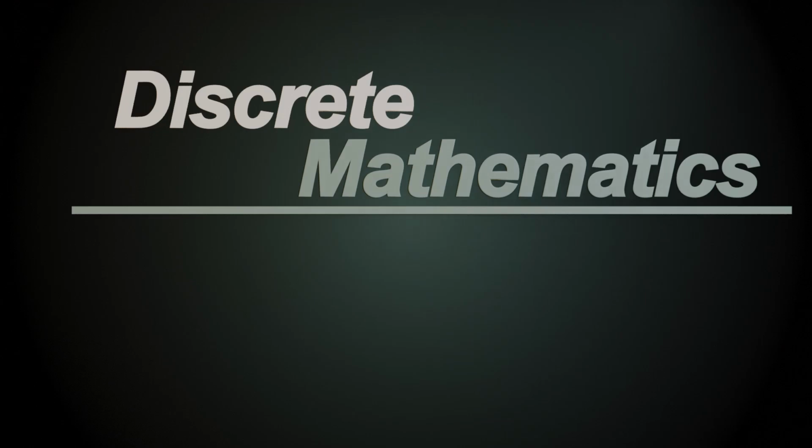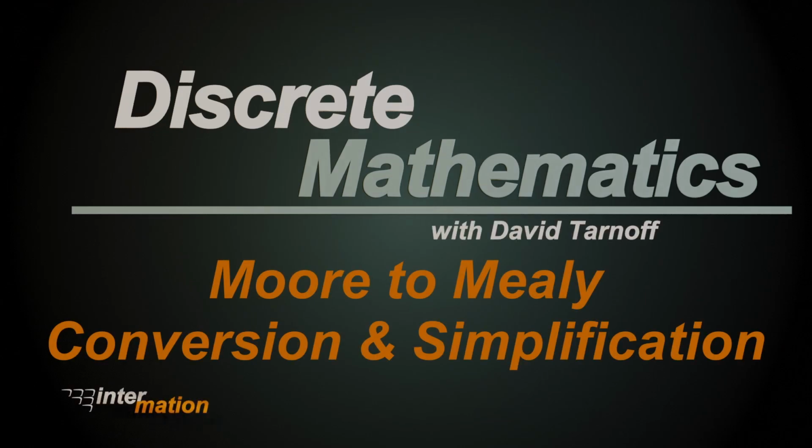Converting a Moore state machine to a Mealy state machine, that's the easy part. Making it worthwhile, that's the trick. A Mealy state machine, where the output is dependent on both the current state and the current input, is a little bit more difficult to design than a Moore state machine, where the output is only dependent on the current state. But it could be worthwhile because the Mealy state machine typically has fewer states than the Moore state machine does.